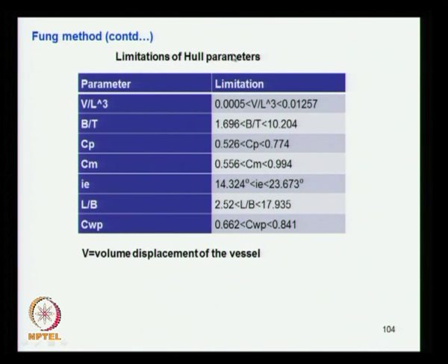So what is this applicable for, what is the limitation of this Funk method? V by L cube, that is volume displacement by L cube, this is a range, V by T this is a range, prismatic coefficient you can see this is a range, midship area coefficient this is a range, half angle of entrance this is a range, L by B length by breadth ratio this is it, and waterplane area coefficient is this. So just look at your ship, if it falls within this range, then you can use Funk's method.